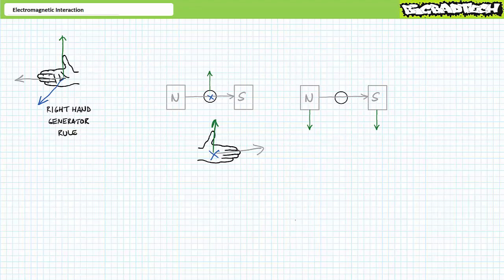All that matters is there exists relative movement between them, and a change in magnetism exists such that a voltage is induced in the conductor. Relative movement is the key. In fact, both the magnetic field and the conductor could be moving in the same direction. As long as they move at different speeds, there will be a change. As an example, asynchronous generators, a subject we'll examine at length in later lectures, have a rotating magnetic field in the stator, and the rotor is rotating at another speed. As long as the rotor exceeds the speed of the stator, there's relative movement and generation can unfold.